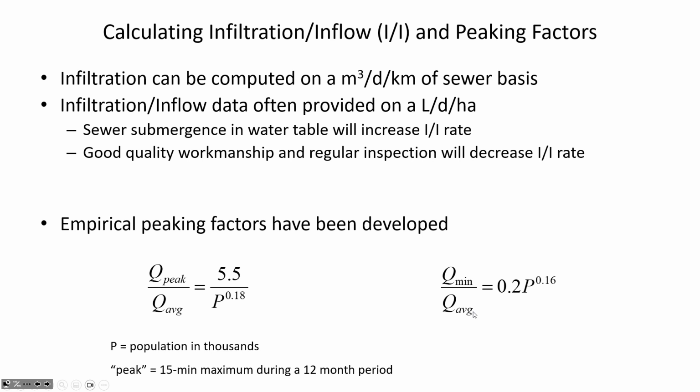And if you have a geographically spread out pipe network, then it takes travel time for when someone flushes the toilet. Water's not moving very fast in these gravity flow pipe networks, usually 2 or 3 feet per second. And so that routing effect, the delay that occurs when someone flushes the toilet and the water has to travel a long distance to finally get to the treatment plant, a bigger population means that the peaking factors are smaller than if you have a small population where people are living closer together, then the peak effects can be more dramatic in small populations.